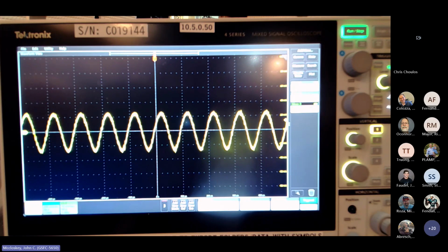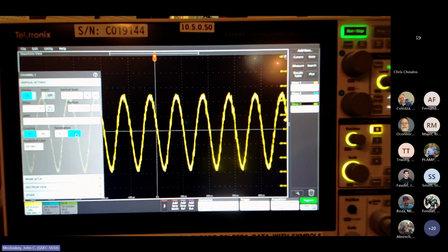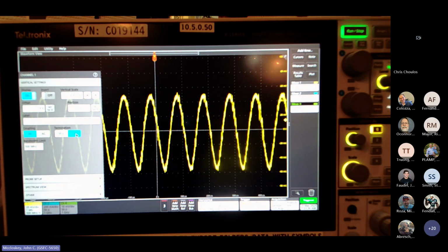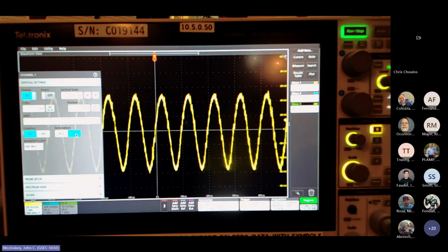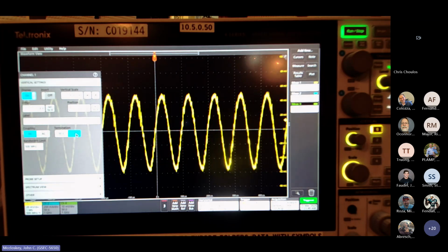Okay. Now what I'm going to do here, I'm going to just do this as we go along. That's into 50 ohms. When we go into a 1 megohm, that'll tell you what our open circuit potential is. And it's about 35, 36 millivolts. So it's about double, right? You still have your 50 ohm dummy load on one end of the fixture, but the other side is going into essentially an open circuit. 99.9% of it, most of it's dropping across that 1 megohm load.